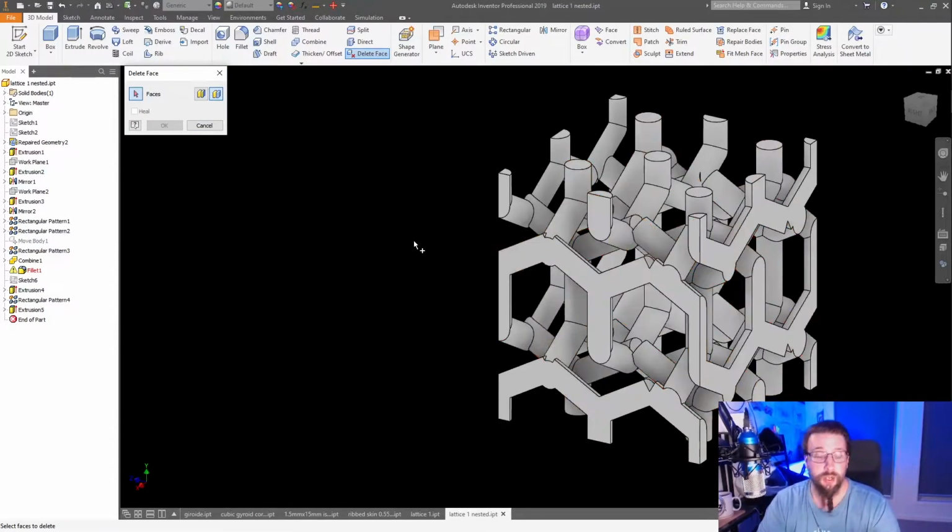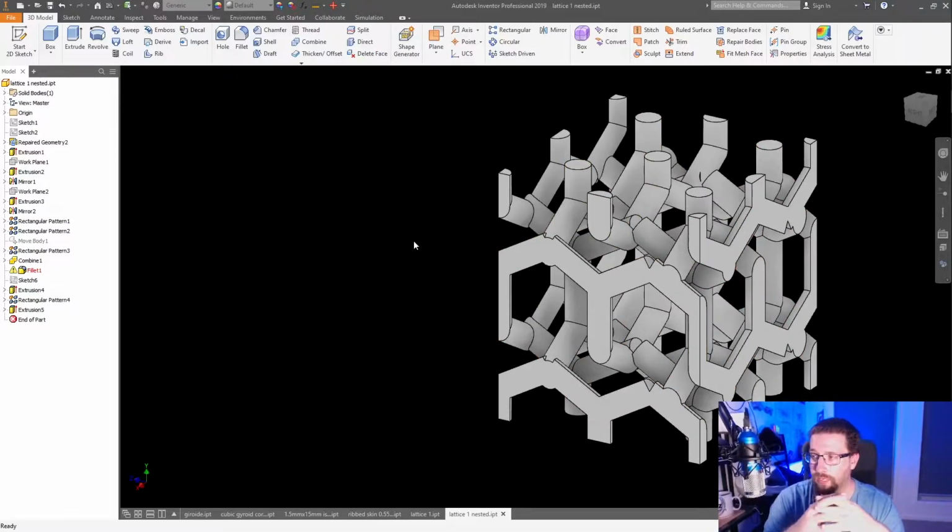Nowhere do they touch, which means that when this is laid out on the inside of a wing, the force is distributed through two lattice structures inhabiting the same volume, the same space, and because the two lattice structures don't touch or interact, the force transfer through them is independent. So you get twice the amount of force transfer through the same volume or space as you do for a single lattice structure, and you are almost doubling the weight. But for the most part, this is a really good system. You can get a great deal of strength out of this for the area and density of the lattice.